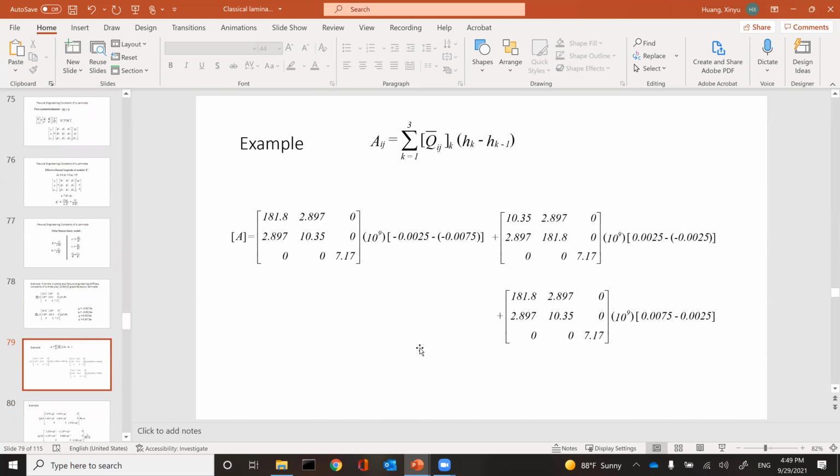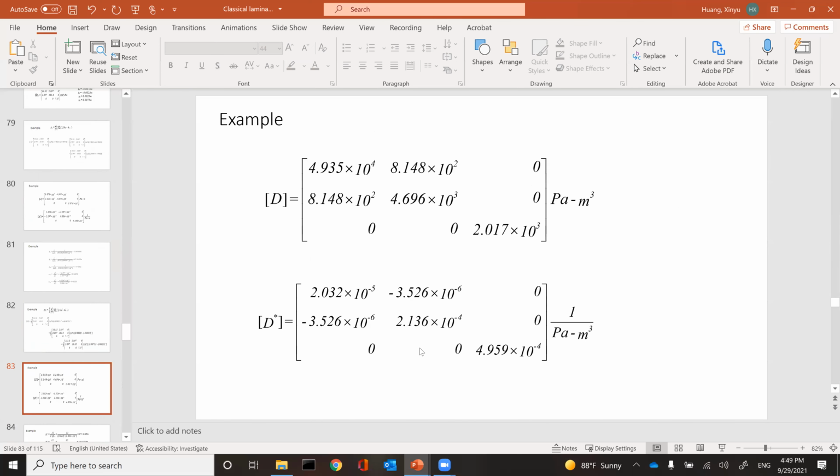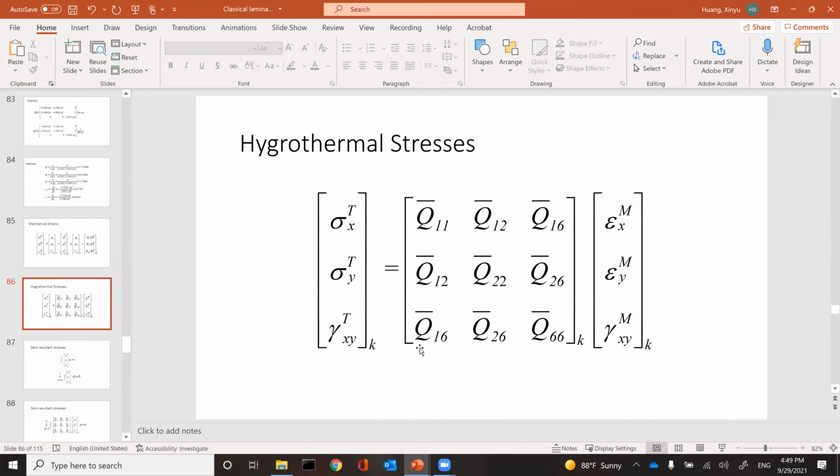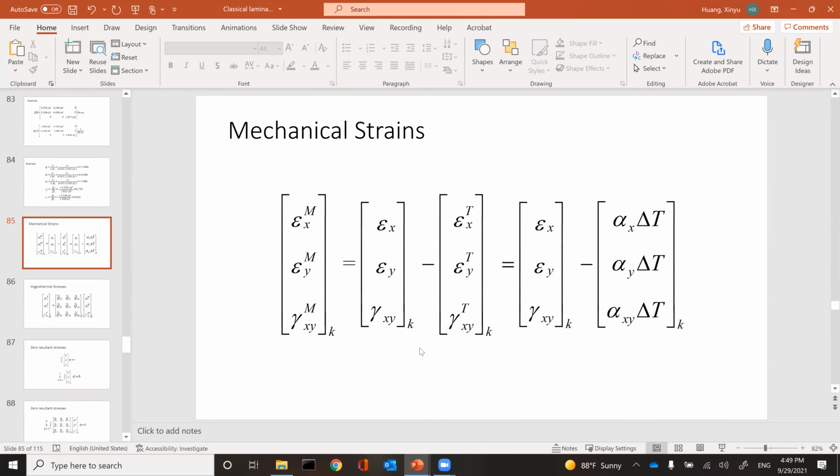Thermally induced stress. It's an interesting subject because the different layers, due to their layup, if you subject the material to some temperature change, all want to expand a different amount in different directions. By now you should have an idea how each lamina wants to expand. Each lamina expands much less in the fiber direction, right? Because fiber doesn't expand as much as polymer. The matrix wants to expand.